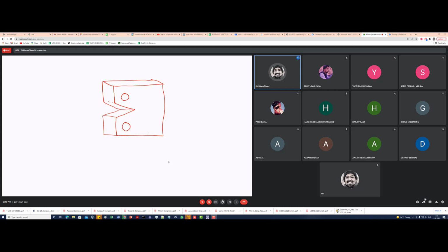It looks like this, okay. And then we have a sharp crack here because of fatigue, and then you load it like this, and then the crack propagates, and then you find out the fracture toughness. So you either find out K1C, or J integral J1C, or J versus delta A curve and all those things, okay.